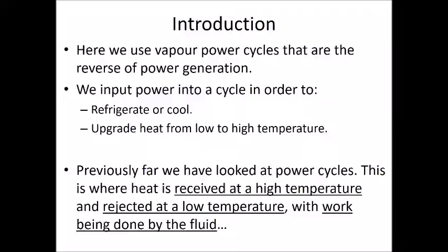What we're doing is we're pumping heat to the outside, which means that it must get cold inside, and that's what we want to do. So the first thing that we would commonly use a heat pump for is to refrigerate or cool a process. So that could be in food refrigeration, it could be in air conditioning, or it could be in process cooling on industrial scales. The other thing that we might want to do, and this is the bit that gives us some confusion, is we might be doing what's called upgrading of heat. So we take heat from a low temperature reservoir and we move it to a high temperature reservoir, all right?